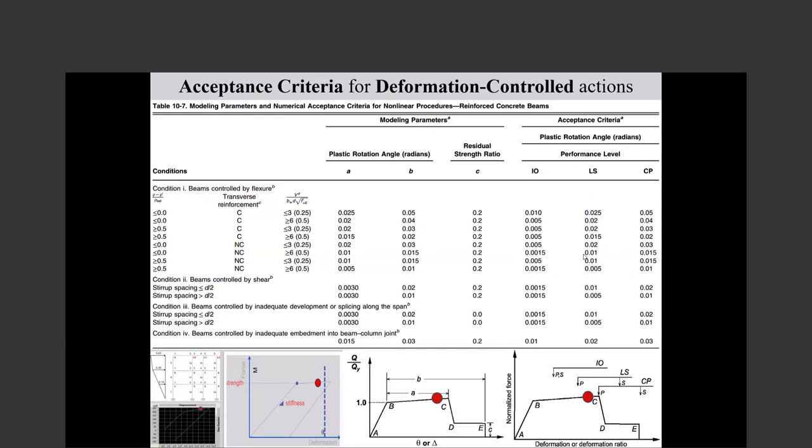They say, you do the nonlinear pushover for the new building. But you should calculate the target displacement. You push the building to the target displacement. Then some of them ask that you continue to 1.5 times the target displacement, and there shouldn't be any deterioration in the base shear top displacement curve in this range.